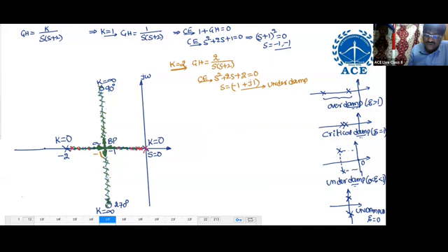So is this the closed loop poles path or open loop poles path? It is a closed loop poles path. RLD, root locus diagram, gives the closed loop poles path, but not the open loop poles path. Be remember. We are taking GH to calculate all the factors.